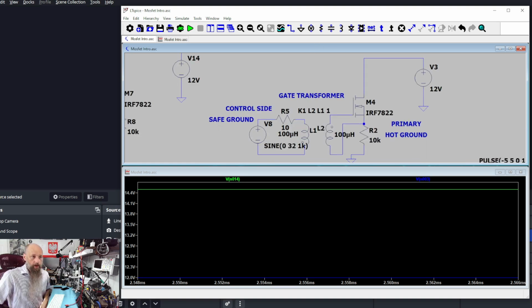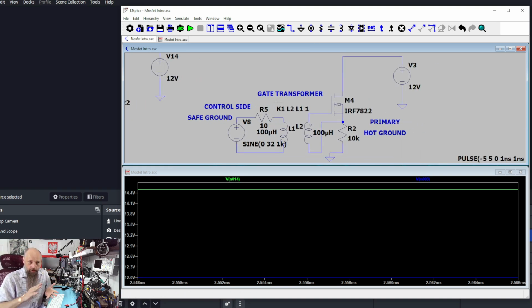Now in power supplies, we are using transistors as switches, and they are cycling, opening and closing at relatively medium frequencies. It could be anywhere from 60 kilohertz to maybe 120, 160. It's going to be always more than 20 kilohertz, and actually roughly more than 40 kilohertz, because if it was lower, it would be audible. We would hear the sounds that are being made by the transformer or other components in the power supply.